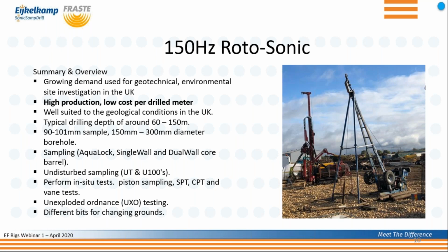We have a range of different samplers and drill bits designed for all types of conditions. More information on these can be found in the second presentation, which we shared last week. You can perform a range of other in situ tests as well: SPT sampling, CPT, vane tests, pressuremeter testing with packers. We have many clients as well who are using the UT100 and U100 systems in between sampling in the UK.